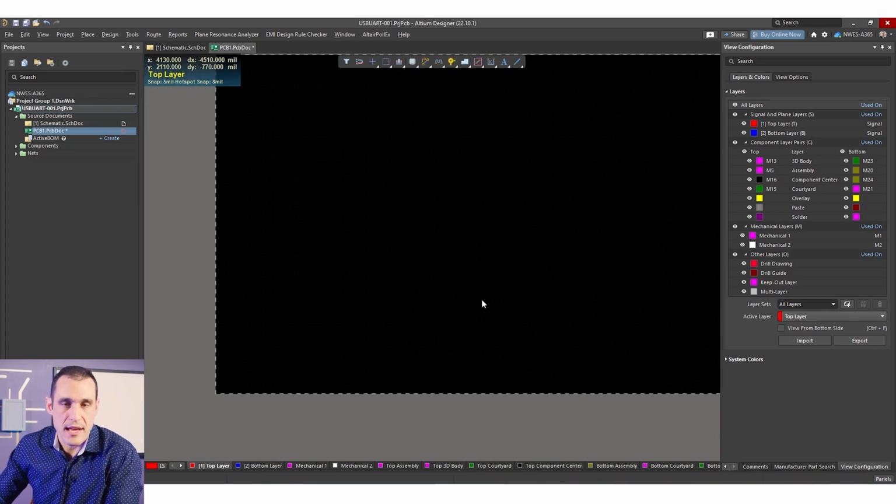Now, we want to set the board size. Setting the board size, obviously, you guys have seen how I like to do it. I just like to use the rectangle and then change the board size definition to match whatever I've drawn in the layout. So I'm going to do that here. The board size of the original module is about 5/8 of an inch by 1 inch. I want to make mine just a little bit longer so that we can fit those TVS diodes on there near the USB connector. Once we do that, we'll have enough room to do the rest of the routing on 2 layers. So we're going to do everything on 2 layers, and we're going to do it at standard thickness, so at 62 mils. So we're going to set this to about 5/8 of an inch by 1.5 inches. So I'm going to leave a little bit of extra room on that long edge. That's going to leave room for the TVS diodes.